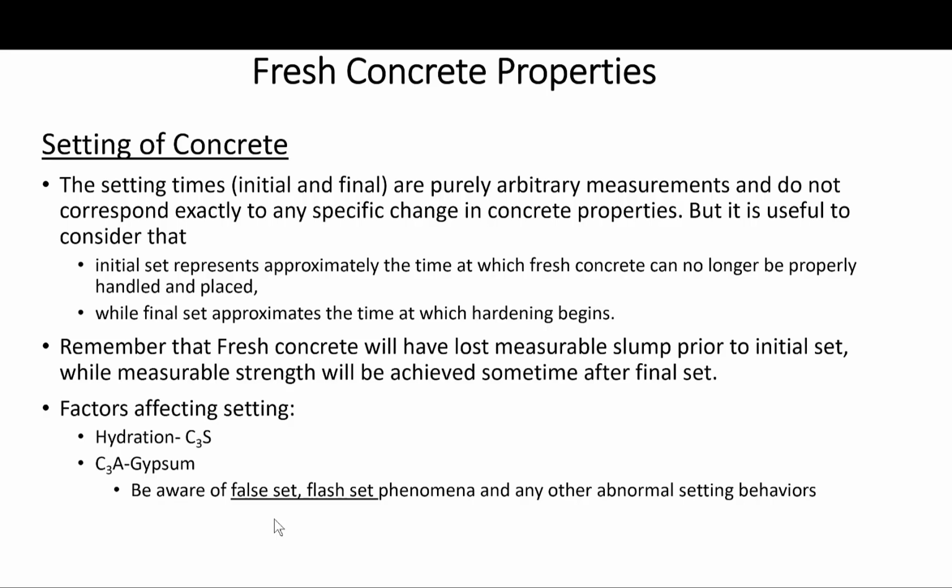Okay, so if this happens and gypsum is basically converted to the hemihydrate, when water is added, the hemihydrate will rehydrate back to gypsum and will form a rigid crystalline matrix. But however, there is only a small amount of plaster in the concrete. Very little strength can actually develop, and the plaster can be easily disrupted by further mixing. Okay, so this is not really a major problem, but it depends.